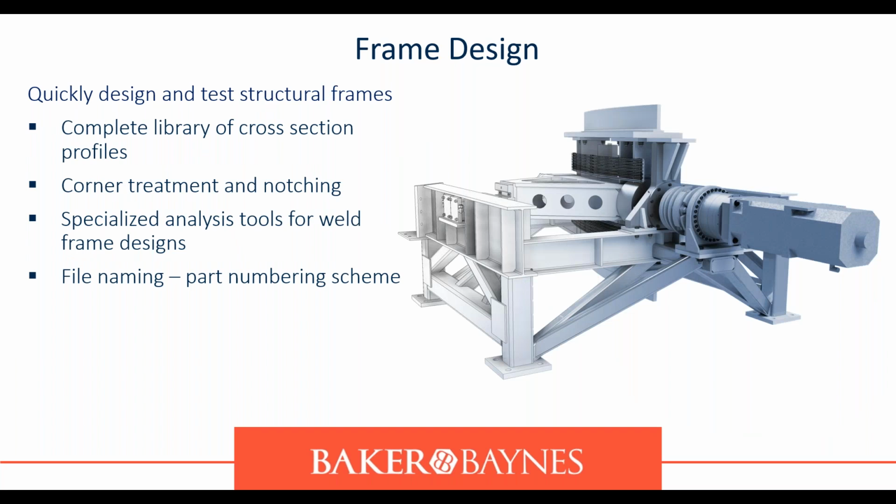Frame design. This is a very, very nice tool to have and know how to use. It saves you a lot of time, so you can quickly design and test structural frames. Complete library of cross-section profiles, corner treatment and notching like miter, specialized analysis tools for weld frame designs, and file naming and part numbering scheme.